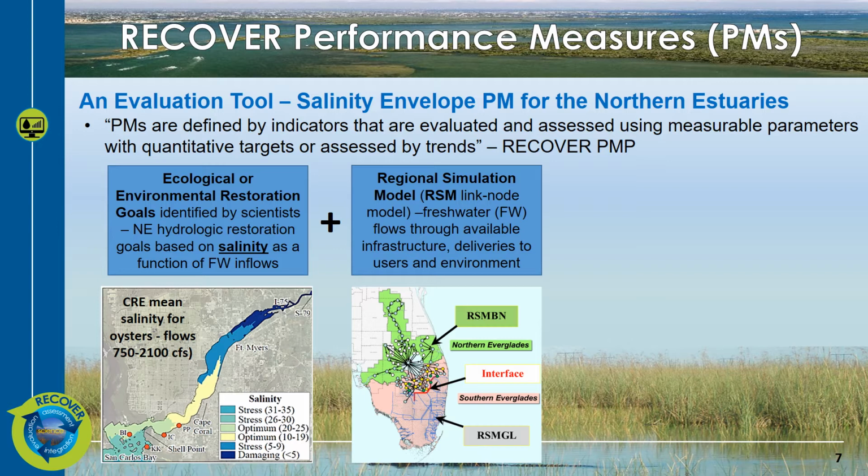Next, these environmental flow targets must then be paired with the Regional Simulation Model, or RSM. The RSM is a link node model that simulates water management operations throughout South Florida by available infrastructure, including deliveries to various users and to the environment. This model can simulate current conditions as well as projections to future conditions, which include new SERP infrastructure, using a